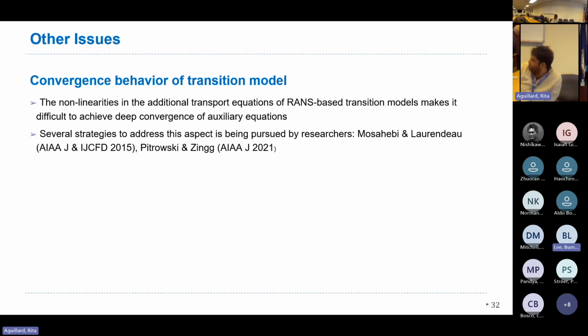Yeah, thank you. I was going to say that's an argument that people like Mike Park always make, that the initial laminar region, the viscous sublayer, is not so important, and the grid resolution there isn't as important as grid resolution immediately above that. But the stability methods guys will argue slightly differently.